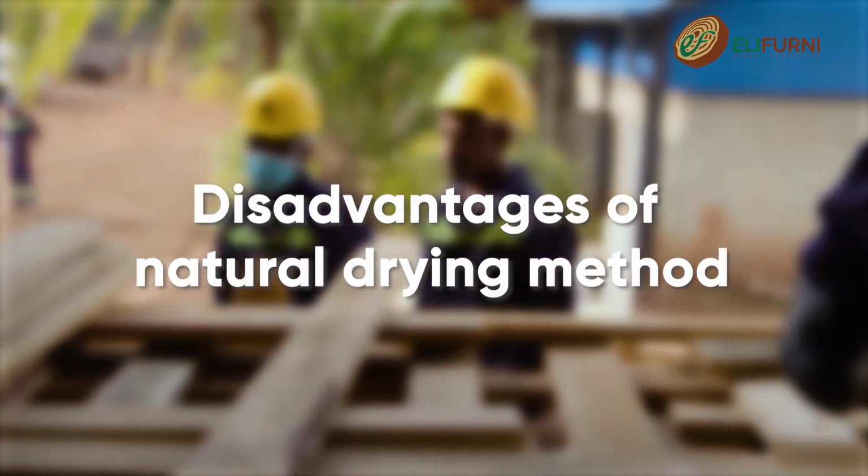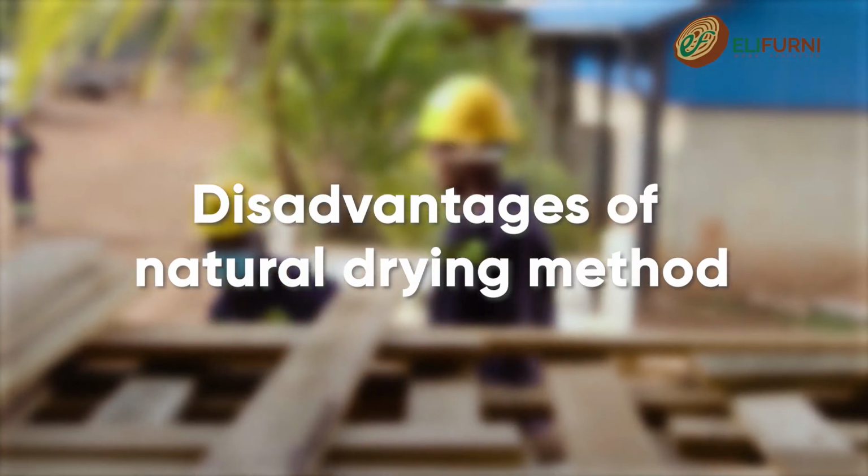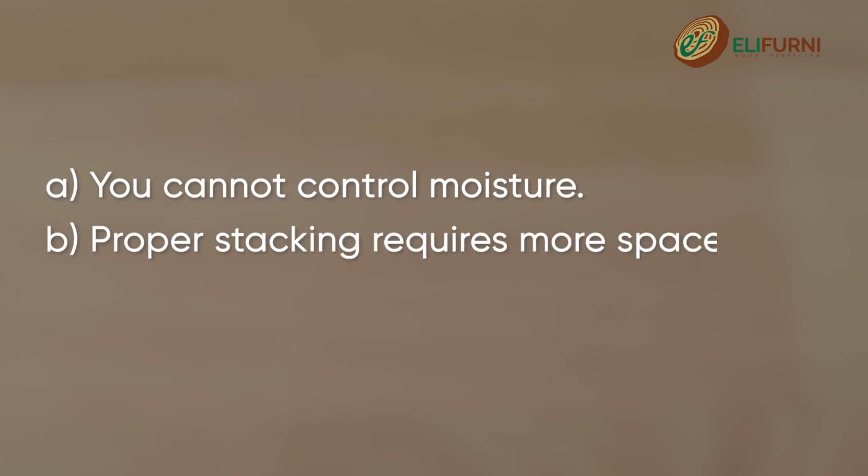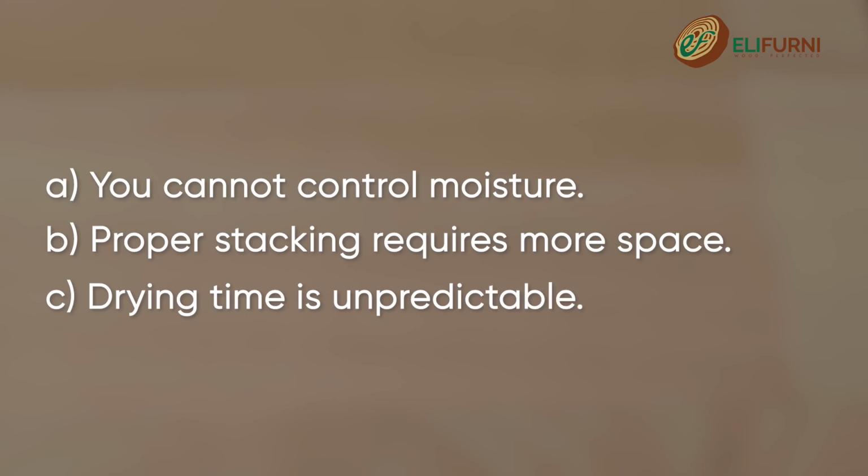However, the downside to this method of drying is: 1. You cannot control the moisture movement in the timber. 2. Proper stacking requires a much bigger space to ensure good airflow around the timber, thus requiring more space. And since this method is dependent on suitable environmental conditions, drying time is unpredictable and can vary significantly.